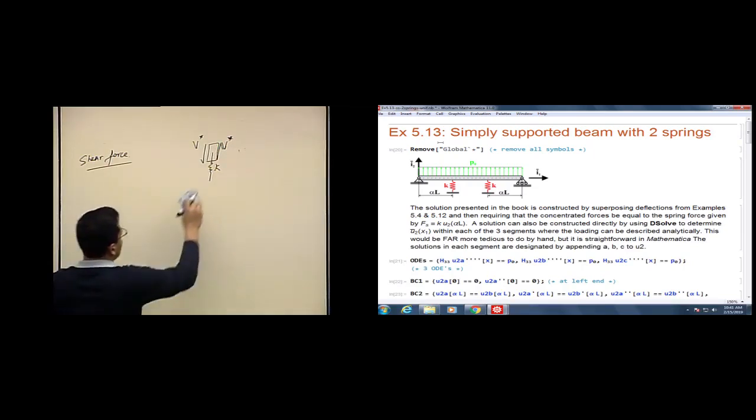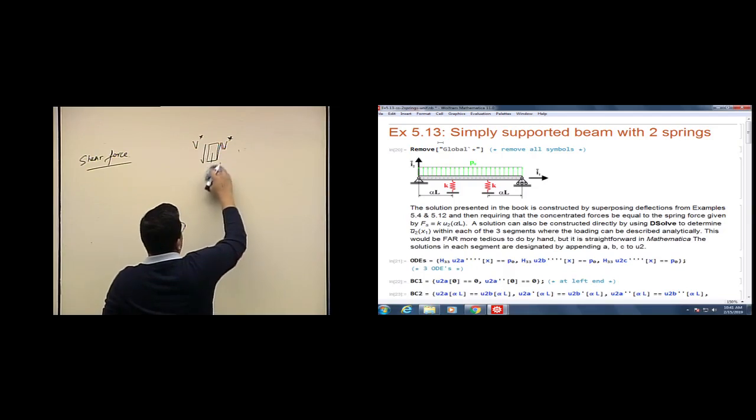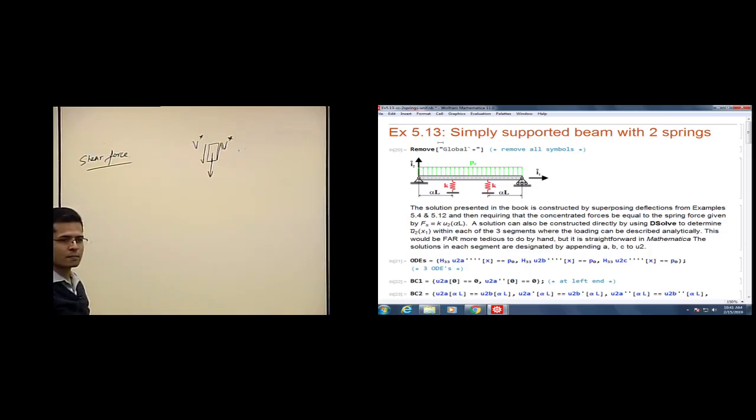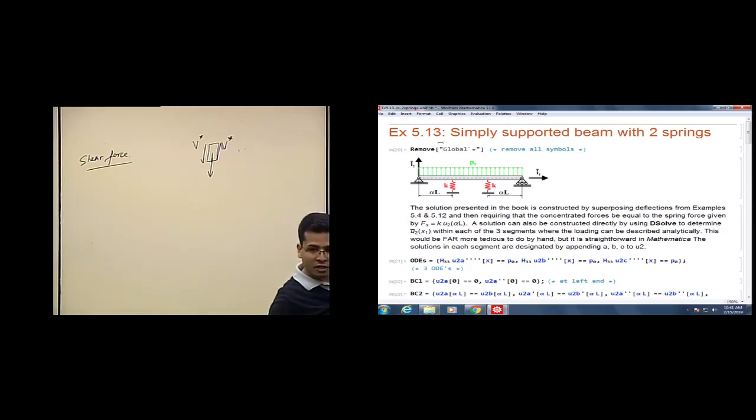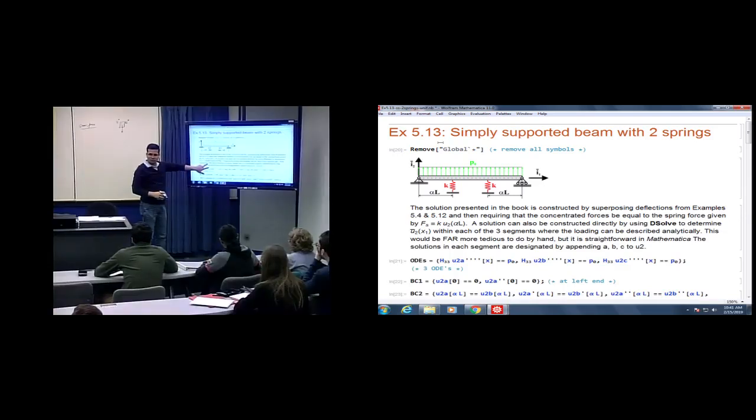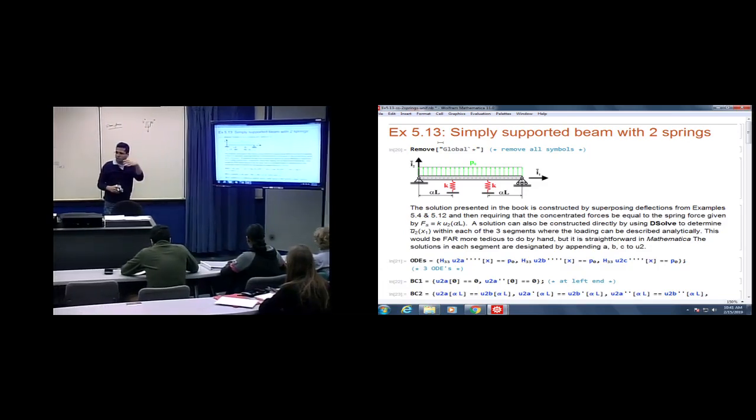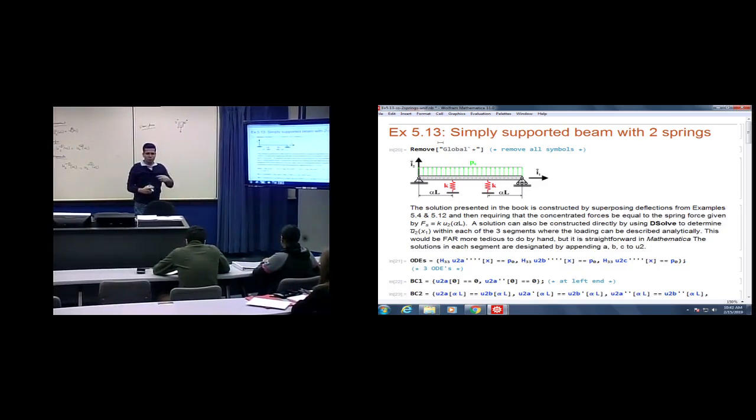And this is not a free body diagram, so let's make a free body diagram where this is a force applied. Considering that the displacement is positive upwards, for a positive displacement upwards, the spring will exert a downward force, right? And similarly, it goes for the rotational springs. You have to look for the positive rotation and then oppose that positive rotation with a moment.